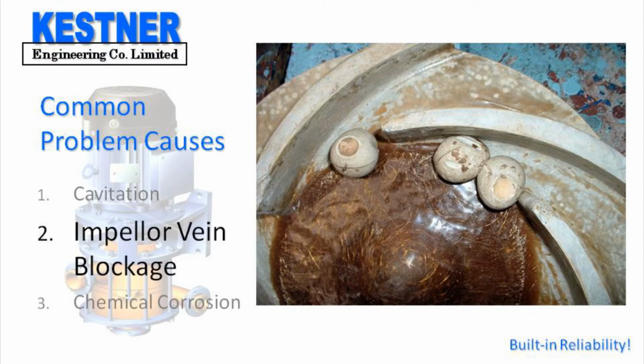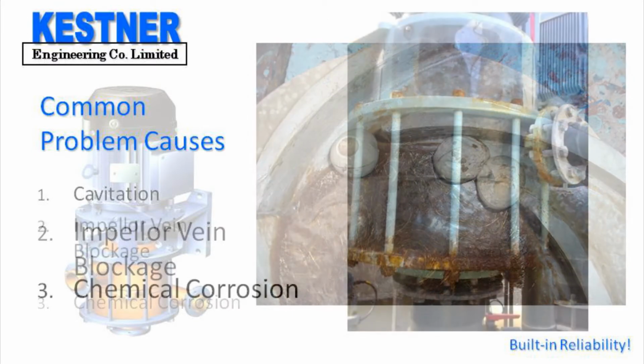Secondly, blockage of the impeller vanes. The photo says it all. It causes an imbalance and therefore excessive vibration, and damages the motor bearings as well as the pump casings.